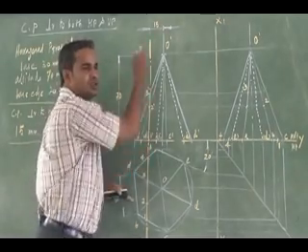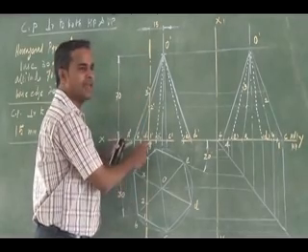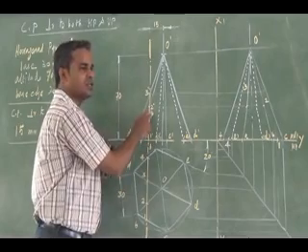The same cutting points should be marked in your front view. Starting from 1, it is a visible base edge. Then 2 is a visible slant edge.